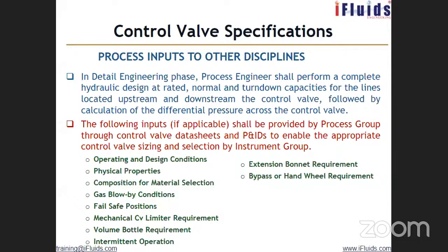Also, for the valve, like the pump, you can do the inlet line side pressure. You can arrive at the inlet pressure to the valve, and from downstream you can calculate the line hydraulics and reach the outlet side of the valve. So the difference between the inlet and outlet pressures will be the pressure drop across the valve. Okay.